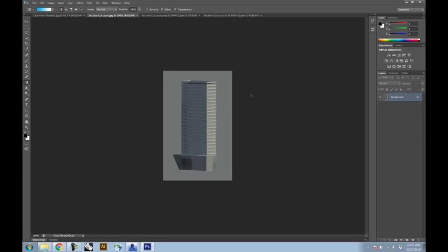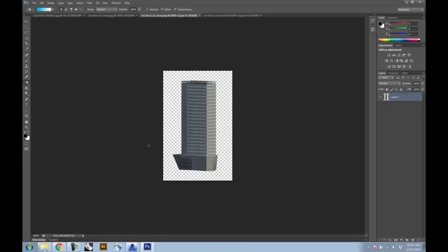So what you see here is that the JPEG has basically a gray background, or whatever you set the sky background to be, whether it's a gradient or a sky. But the PNG and the TIFF both come in with transparent backgrounds, so it allows you to use the transparency. You can see here through my parapet, I can see through that and into the background. It's going to help a lot when going to position this content into the skyline photo.